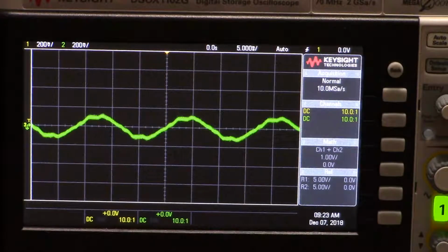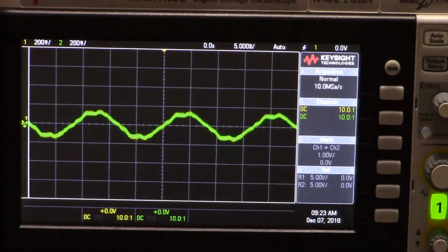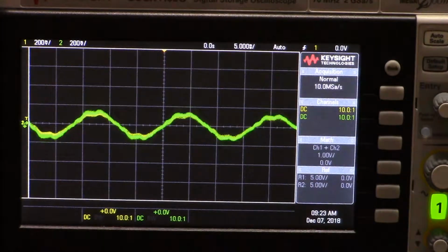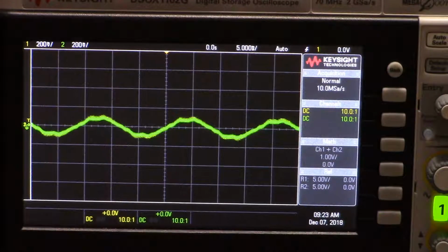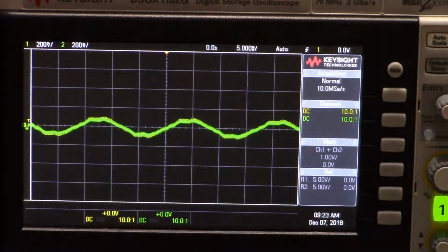So I'm setting up the yellow lead in one set of traces, doing a double check to make sure I've plugged it in correctly, the green into another set, and then I'm going to use one jumper wire on the breadboard to make sure that I have connected the grounds together.